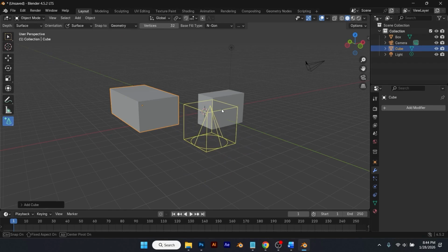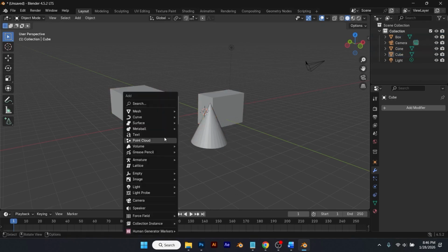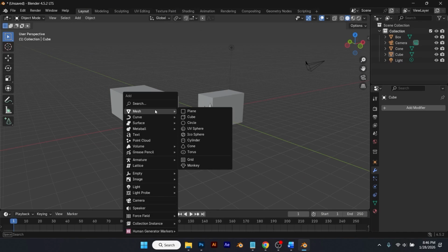In Blender there are multiple ways of doing one thing. Alternatively, we can add objects using the shortcut key by holding Shift plus A. This displays the Add menu. When you hover over Mesh, you can see we have other objects we can add to our scene. Aside from that, there are a lot of other things we can add directly from the Add menu.